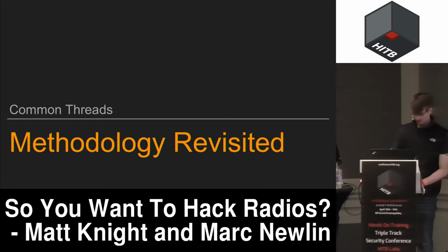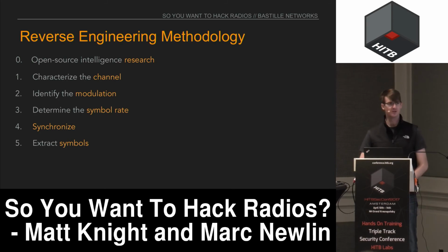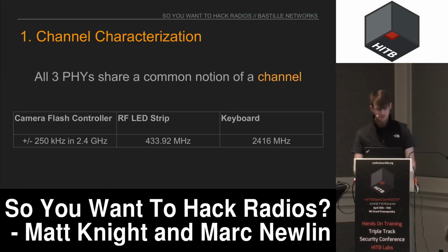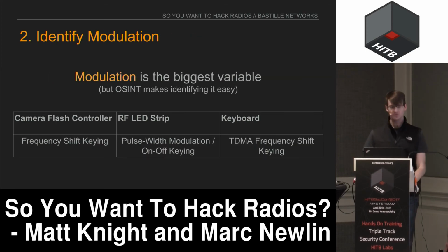Okay, so let's draw some conclusions and tie this all up. We proposed this reverse engineering methodology that we've shown can be applied to a number of wireless PHYs to make the process of reverse engineering them quite a bit simpler. We've established that all 3 of these PHYs share this common notion of a channel. Whether it was on-off keying, pulse width modulation, or FSK, they all occupy some predefined amount of spectrum that can be characterized. They all use some type of modulation, and this is the biggest variable, but by relying on open source intelligence, we can make the process of discovering it easy.